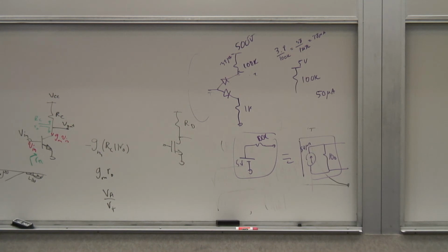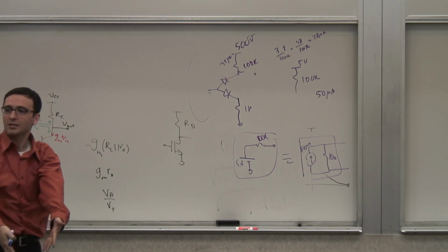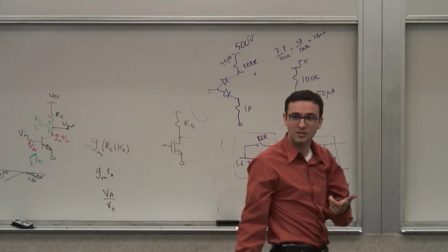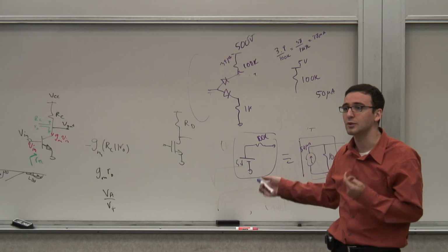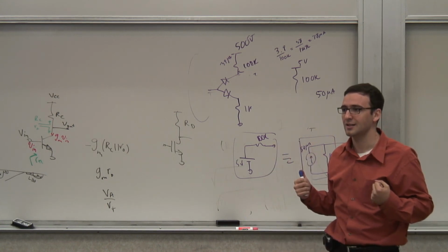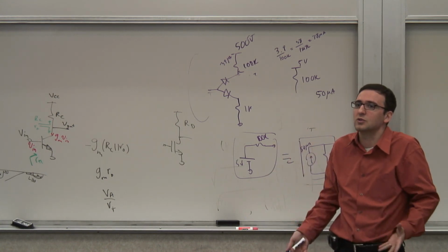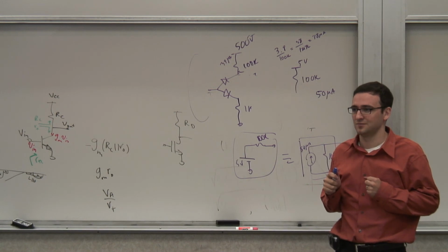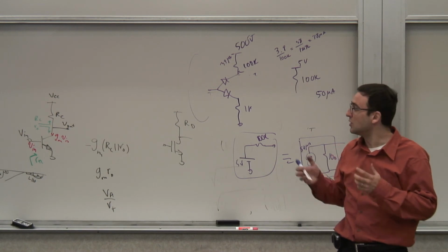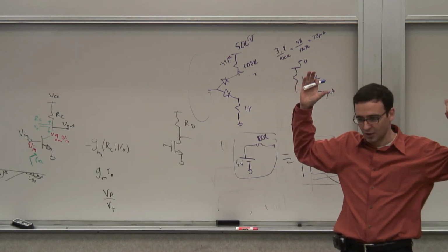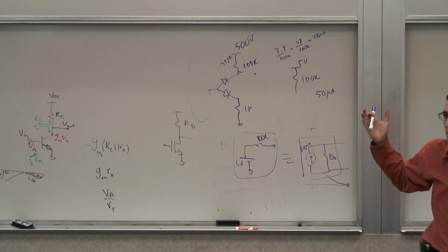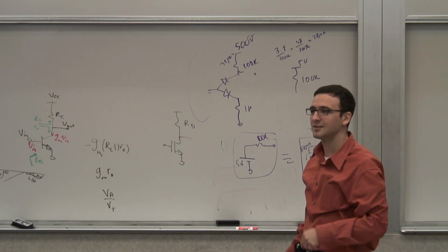Both the collector and emitter are pouring a lot of electrons into space. They're dumping electrons. And that's why once the bipolar transistor goes into saturation, it takes a heck of a lot of time for it to come out of saturation. It's extremely difficult. It takes a while for it to turn off, because you've dumped a lot of charge into the base. So if you remove everything, the charge still has to go somewhere. So it carries more current.